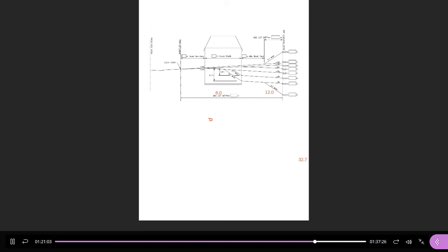Suppose your existing ground was between negative 2.32 and positive 3.89. Then what I would do is a full walkout. So I would design the elevation at the front, the elevation at the back is a full walkout. And then I would come down at 3% and I would come up at 3 to 1 from this backyard elevation. See existing, I would come up at 3 to 1 and I'd have a little extra usable backyard. Right? That's a bad drawing, should be parallel, but that's what I would do. Okay, so we can talk about what the design should be, right? I would come up parallel to this line here at 3 to 1, and there's my backyard point. So now I have not minimum 7.5, but a little extra usable backyard.